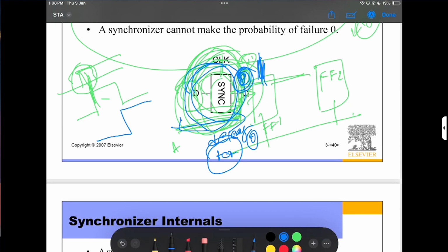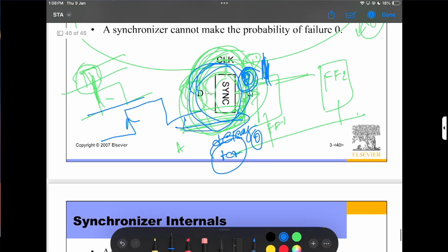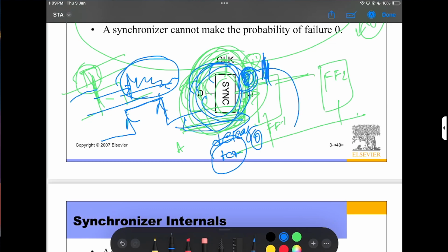If the clock is high and positive edge triggering, I already have 0, but my other input changes after the t delay and goes to 0. But at that time my circuit does not get the positive trigger, so whatever the output of this will not appear in this flip flop output.